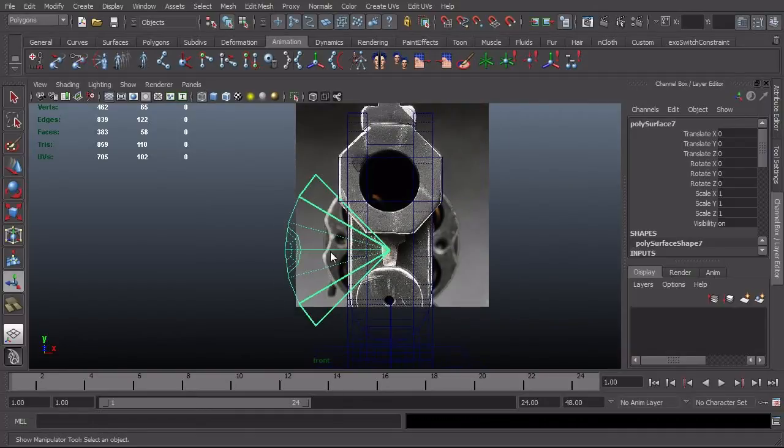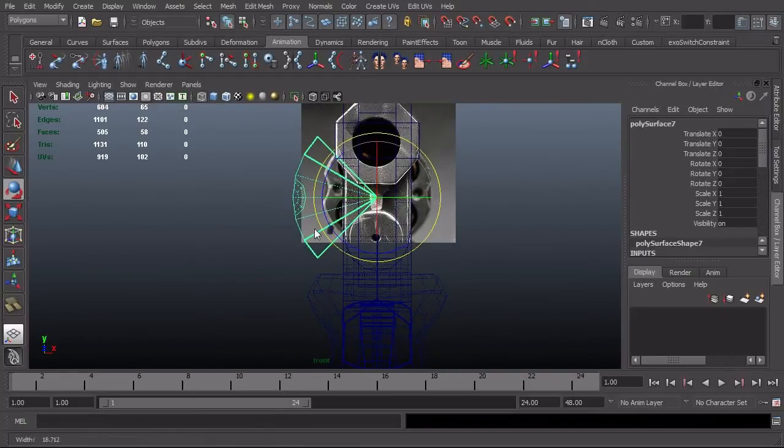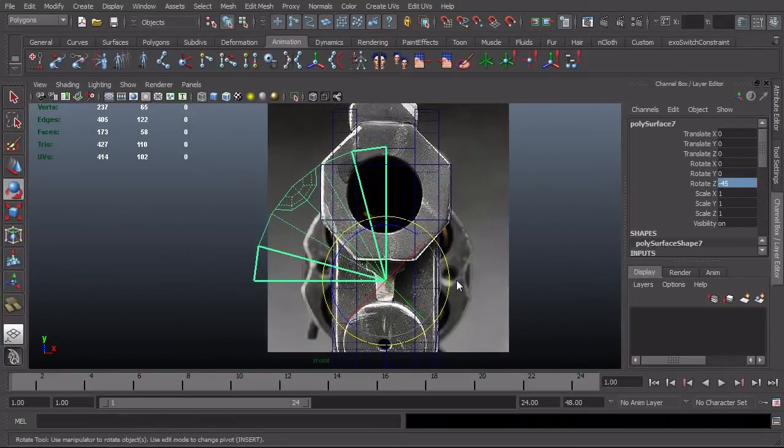This thing is no longer part of the group because of the Boolean operation. So I need to go ahead and just recenter this guy. So I'm just going to snap this up. Again, those points are really handy for knowing where the center of the cylinder is. And then I'm just going to rotate this thing -45. And that'll put it right back to where it was.